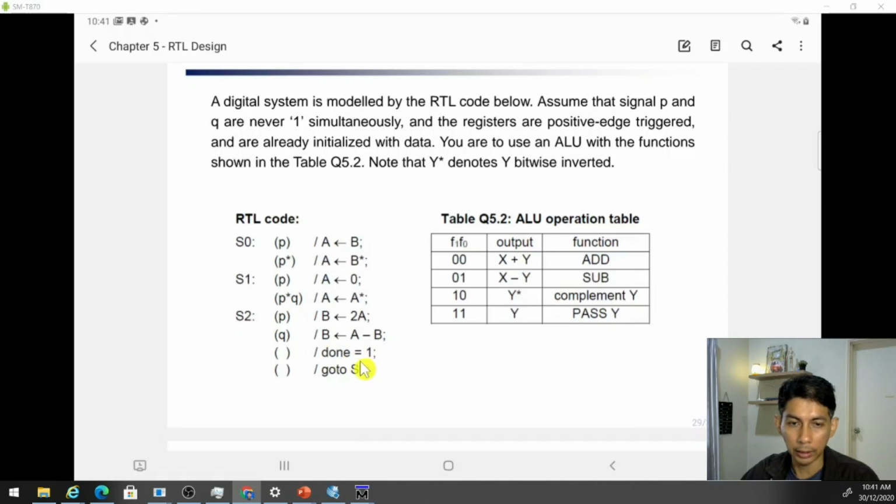All right, this is actually an important signal in digital design. When we finish any operation, we need to generate the done signal. All right, because this module, this circuit will be connected to other modules as well, and will communicate with them. So if the operation is finished, we need to tell other modules that it is finished.